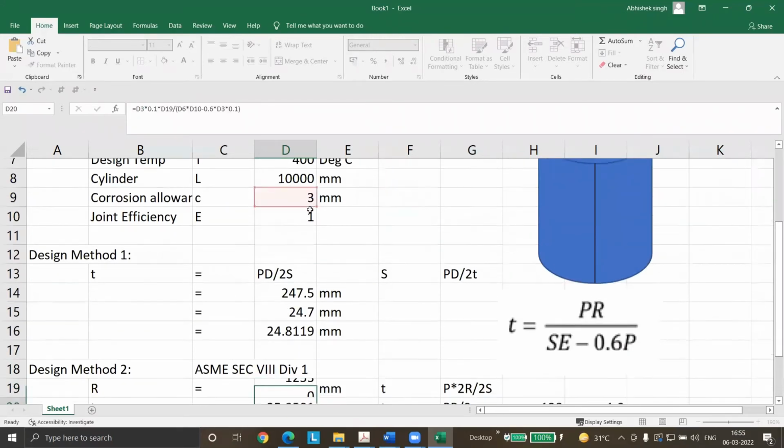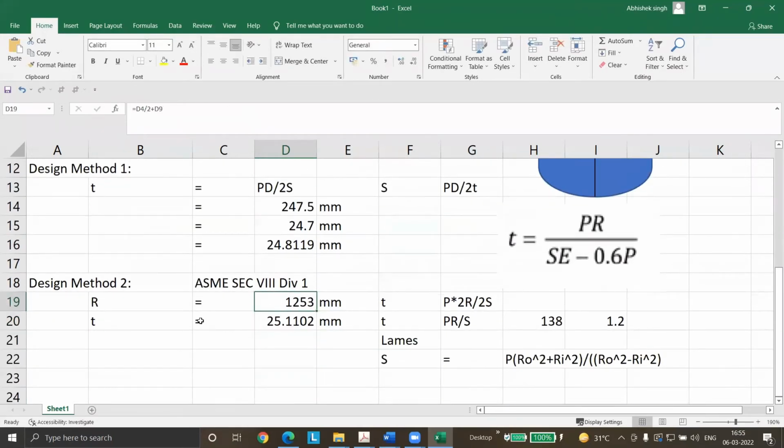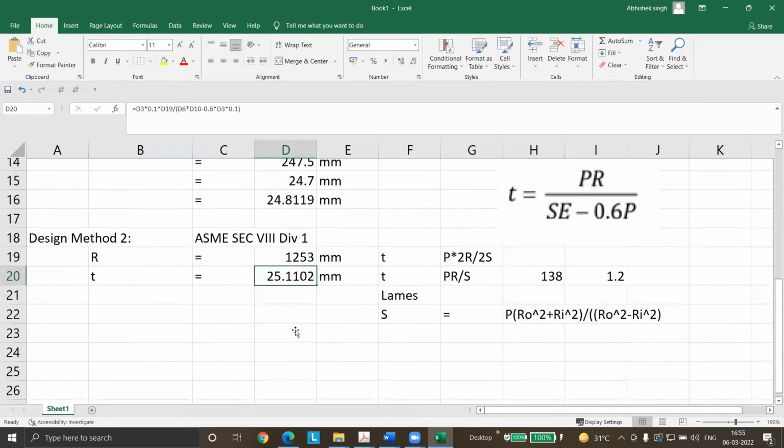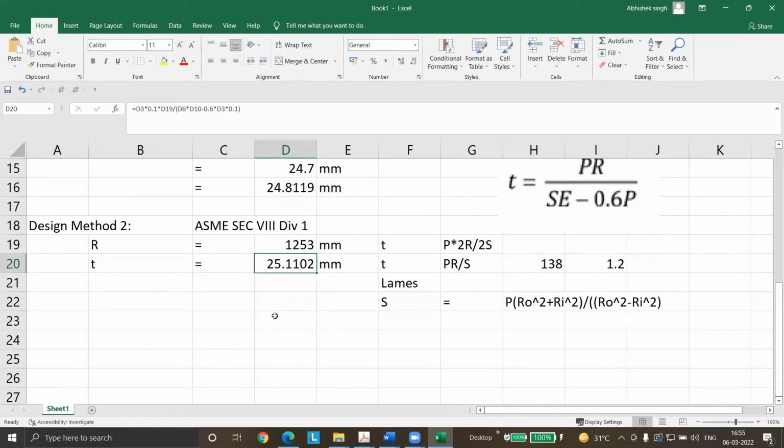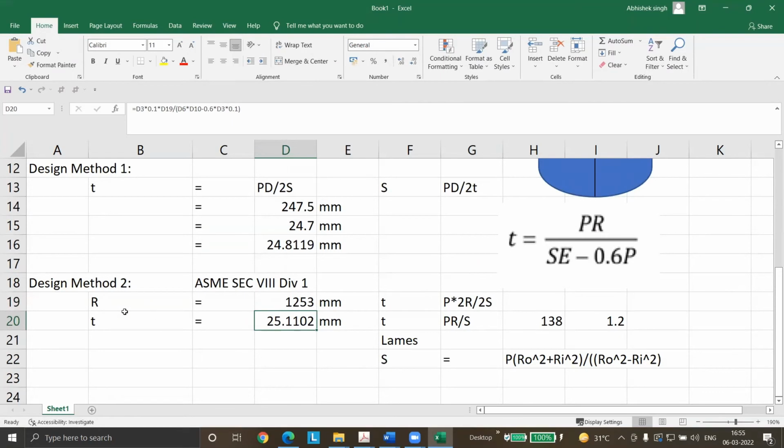Okay. So if I'm using R, I need to add the corrosion allowance. Very good, Ahmad. So R, like we have already studied, all the formulas which we are going to study have to be in corroded condition. So this is the thickness which we will get as per code. This is based on the circumferential stress formula.